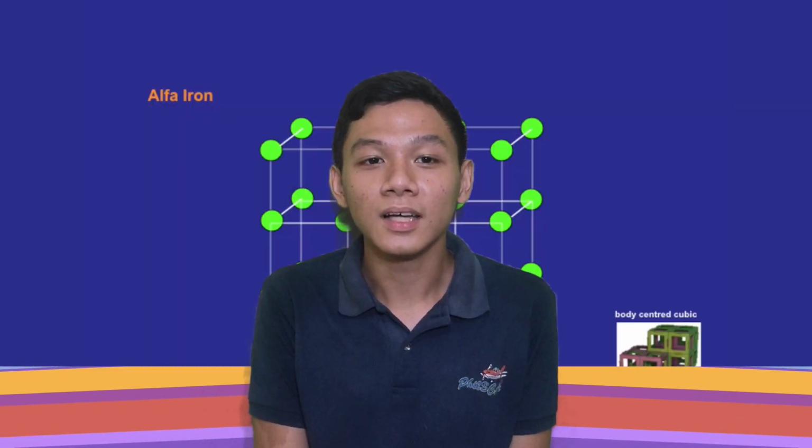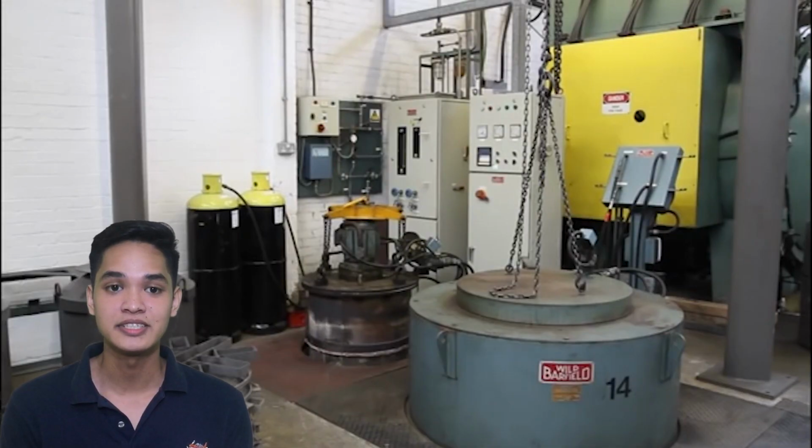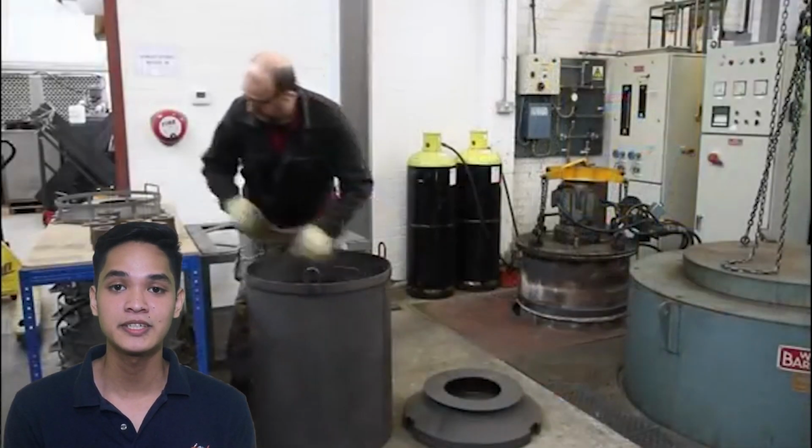Nitriding is unlike other case hardening processes in that before nitriding, the part is heat treated to produce definite physical properties. Thus, the parts are hardened and tempered before being nitrided. Most steels can be nitrided, but special alloys are required for best results. These special alloys contain aluminum as one of the alloying elements and are called nitralloys. In nitriding, the part is placed in a special nitriding furnace.